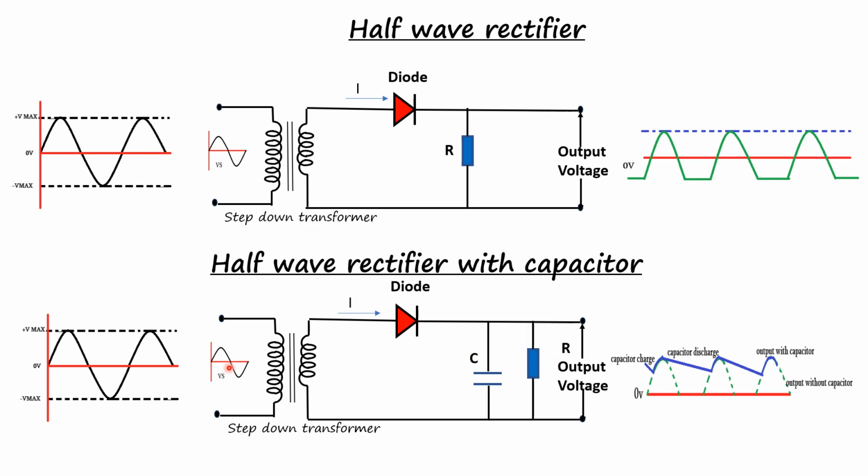During the negative half cycle of the AC input, the diode is reverse biased and it will be acting as an open switch, during which the capacitor supplies the energy stored in it. So we can say that the more the energy storage capacity, the less the ripple content in the output waveform.